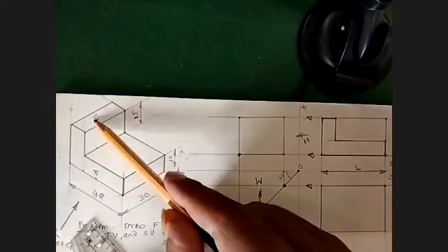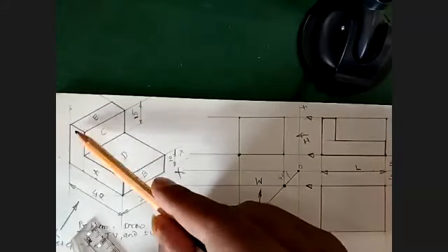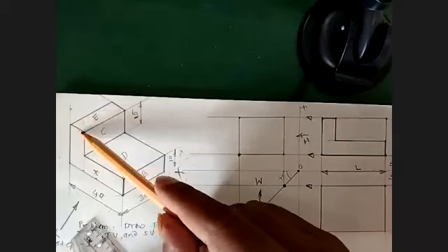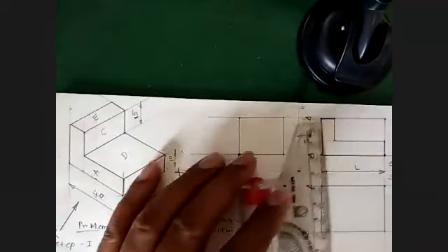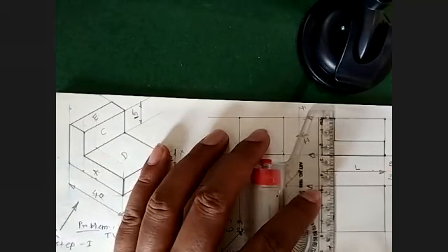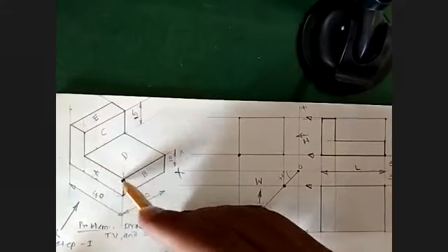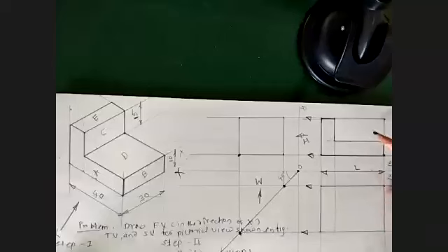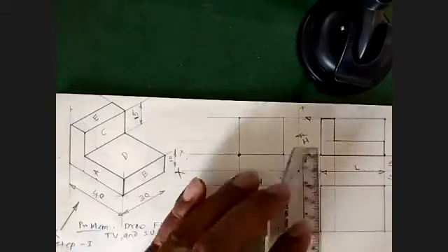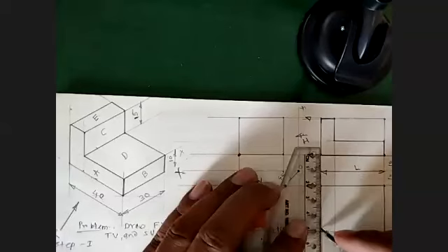Yeah. E, this surface, which is seen in top view, has a concern in front view up to this length only, right? Up to this length. So what I will do, I will take this projection, considering this edge here, and I will project it. Okay. Then for D, in front view, this much length is the concern, and this surface is visible. So already this surface is coming here, nothing complicated as such. So what I will do, I will make it dark.